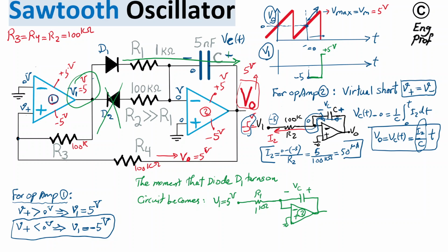and this time we have initial condition because V out got to 5 volt already, and on the other side we have virtual ground, so this cap has 5 volt on one side, 0 volt on the other side, so there is initial condition. The current that is now passing through the cap like this has to work out the initial condition and change the polarity. So there is an interesting phenomena going on.